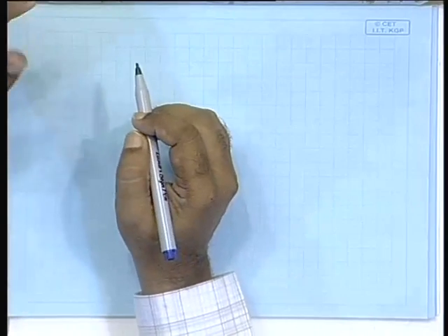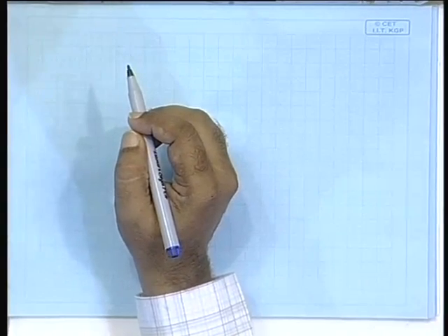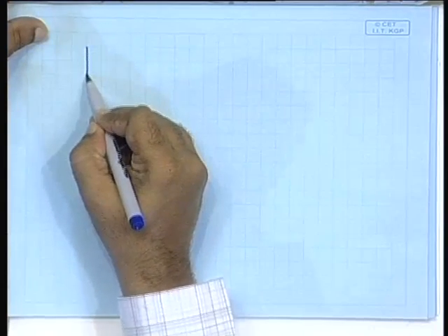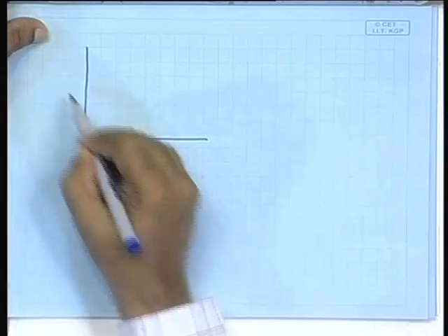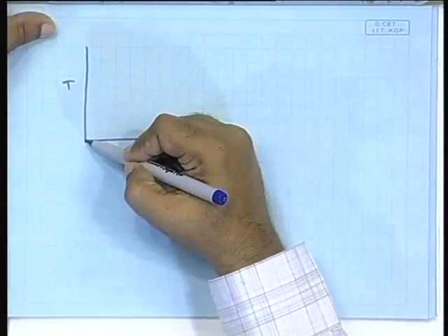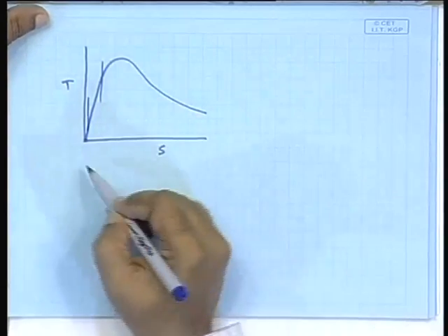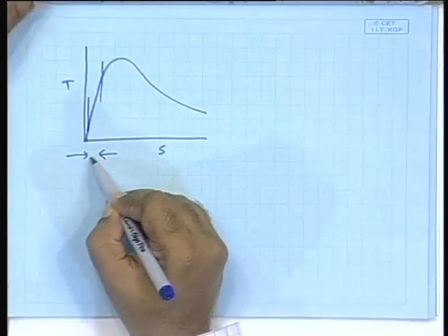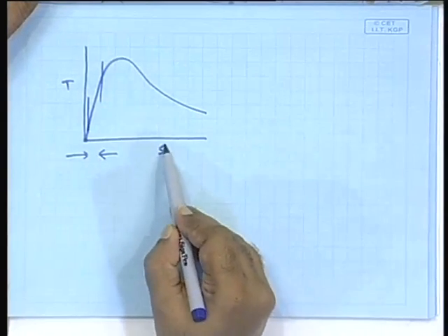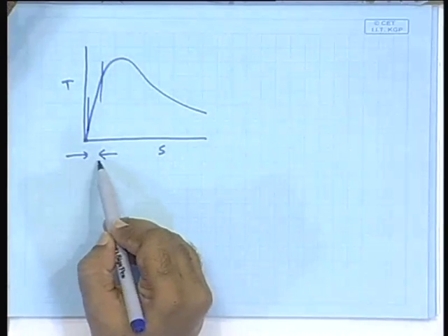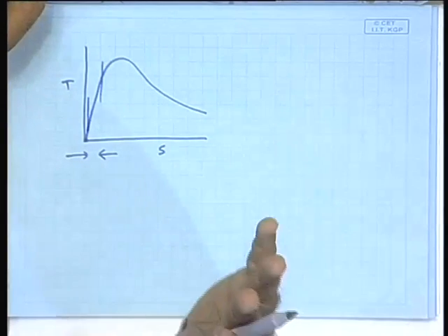But the disadvantage is, firstly, if you connect it directly to the grid, then at least theoretically it does supply a constant frequency, though it can rotate, but actually it cannot, because of the torque slip characteristics of the machine. It will be like this, and because it can operate only in a small range, it will have only a very small range of slip that is feasible, and since slip is given by the speed, only a small range of speed will be feasible. So, the machine will be able to operate only within a very small range of speed variation. So, that is for the grid connected.